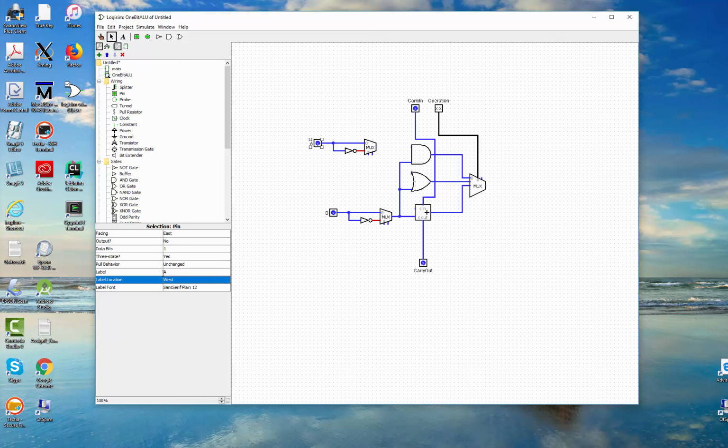A. And have that go into the top of the AND gate and the other parts, the OR gate and the adder. The only two things we have left to do is to put the A invert and B invert. And let's go ahead and do the muxes.